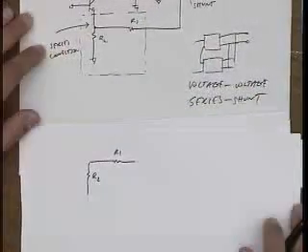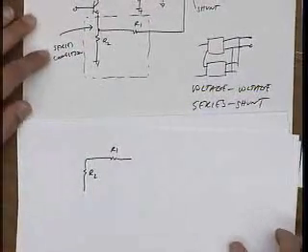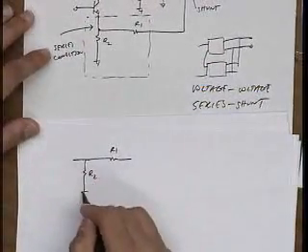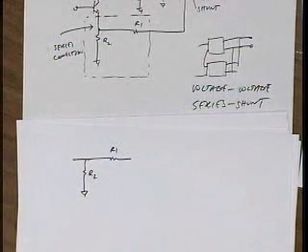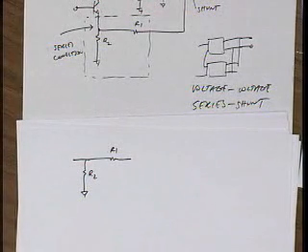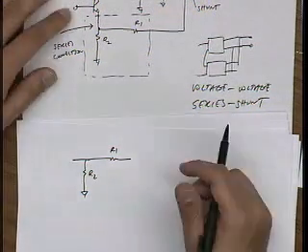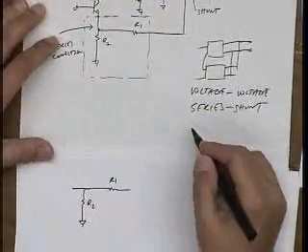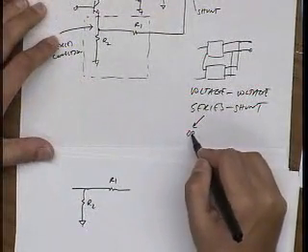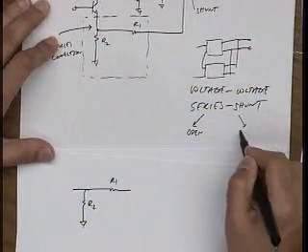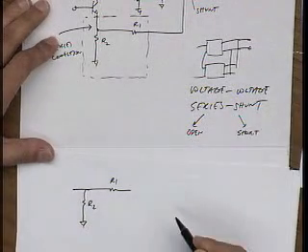Okay, so now you might be in trouble. Let's say you're on the test and you're like, oh god, H parameters. How do I calculate H11? Is it short on the output or is it open? God, I just can't remember, right? So what's the easy way to remember? Yeah, Debo? Series is open, shunt is short. Yeah, just do a transformation. The transformation is series means open, shunt means short. Right?